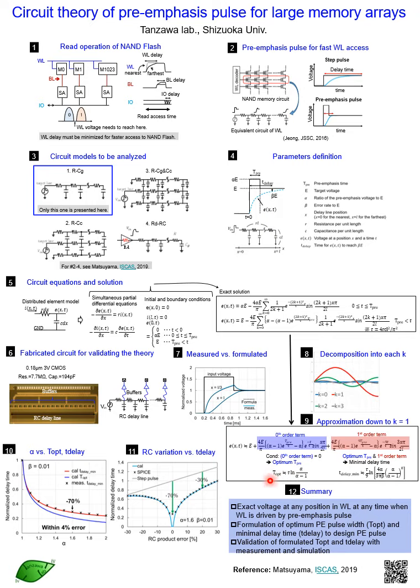You input this information here, then the minimum delay time is given by this equation. Minimum delay time includes RC time constant and alpha and beta. So depending on your definition for beta, you input those parameters here, then you can estimate the actual delay time for the slowest node of the word line.